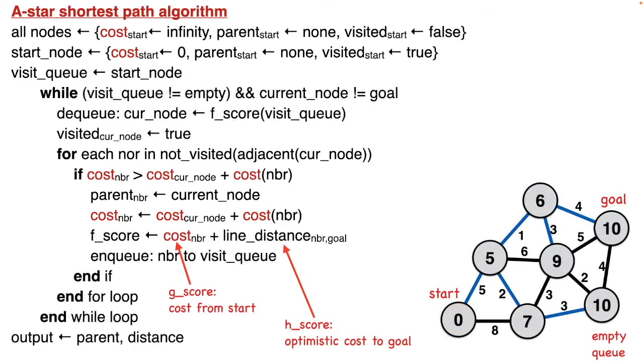And so in particular, we could then apply our A* shortest path algorithm, for example, to find the path of minimum cost that would then result in our robot being able to move smoothly and safely, avoiding collisions within the configuration space. Now, one final nuance within this algorithm that we should address before we go and implement it in this generalized form is the sort of issue that we ran into in the case of 2D planar motion planning, which was we had a fixed graph of just north, south, east, and west adjacency cells.